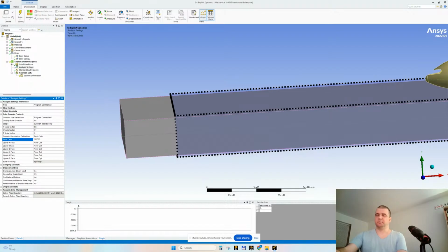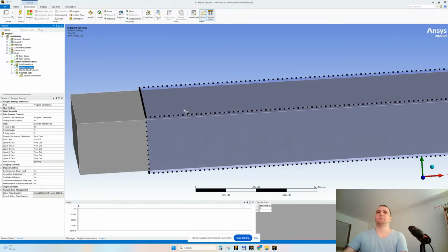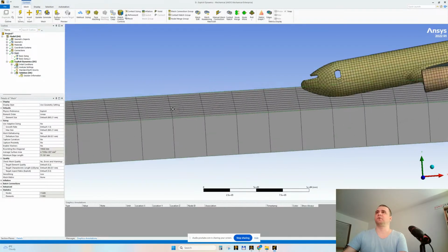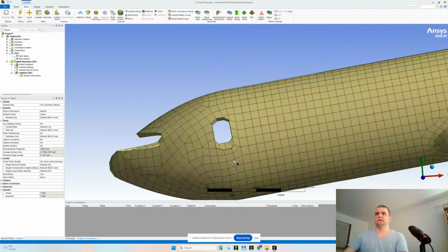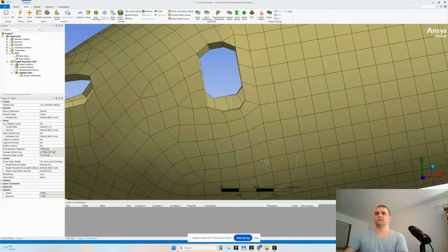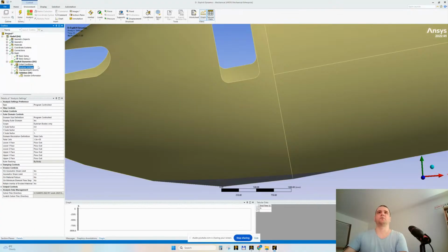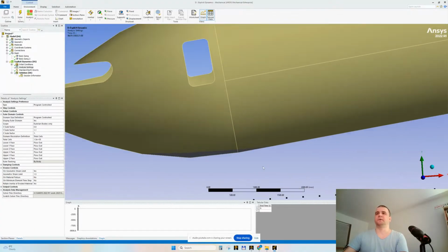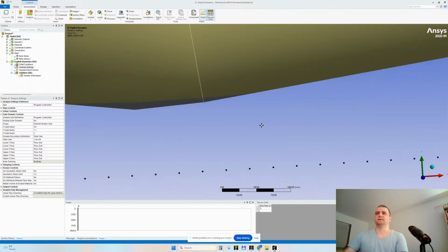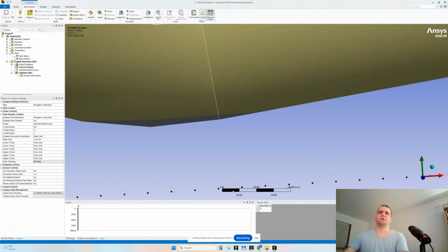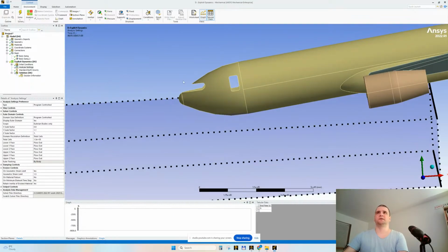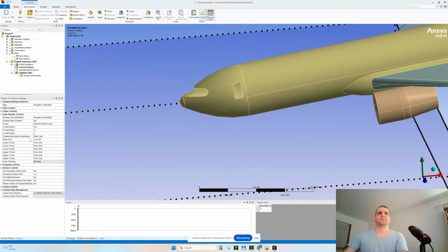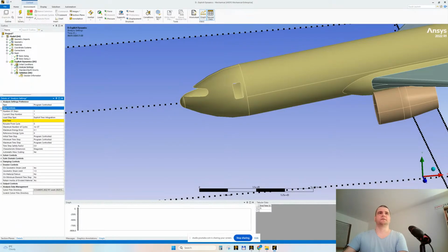Can I make it, I don't know, maybe 100? And I'm looking at the resolution, yes? I need to somehow correlate the element size, yes? 250. I need to somehow correlate it with the frame, with the discretization. And I see that the water discretization is around 250, okay? We need to be conform. We need to have similar element sizes, let's say. So let's leave these like this.